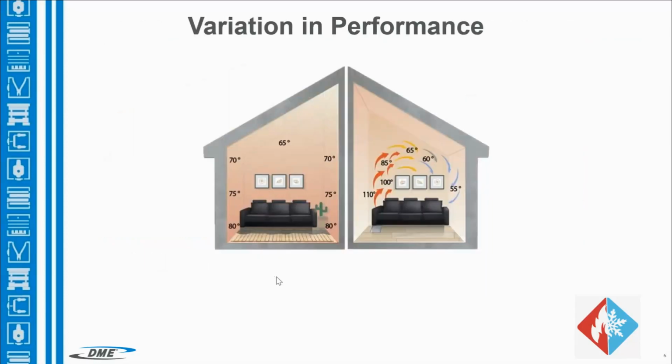So the advantages and disadvantages of systems really boils down to variation. In molding, that's really why we have jobs. We have variation in polymers. We have variation in temperatures. We have variations in our processes, our equipment. And all these variations have to be managed depending on how critical your part is, what materials you're running, and the scrap rate and efficiency that you're trying to achieve. And that's where you've got to take a step back and look at your system as you're designing it.